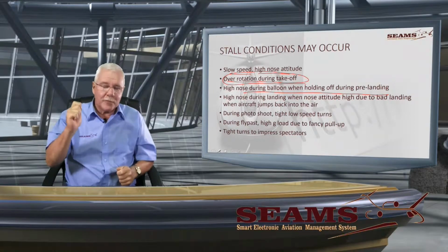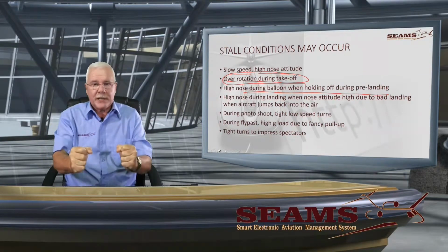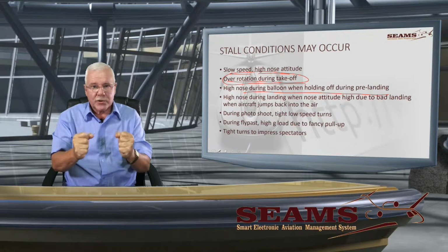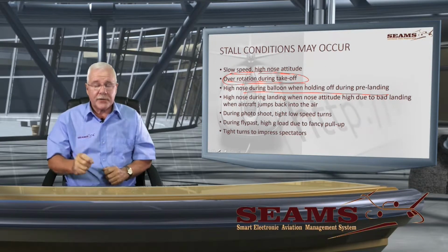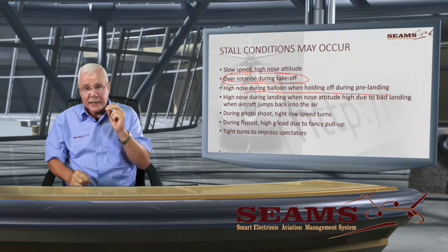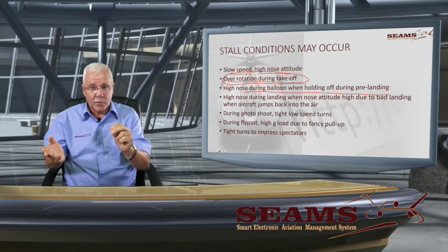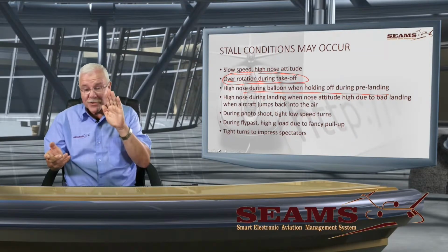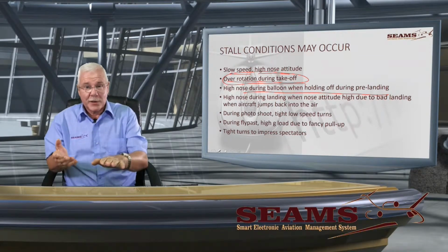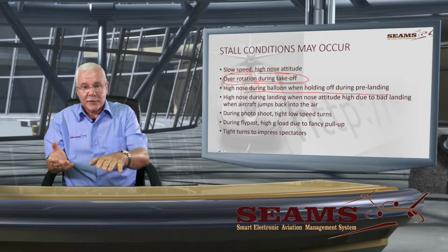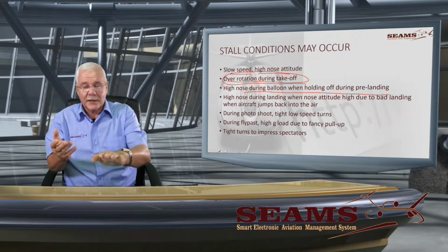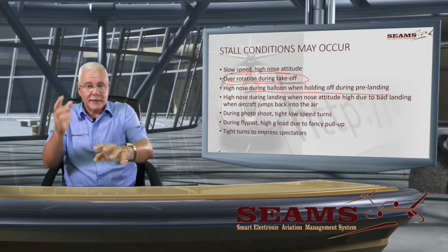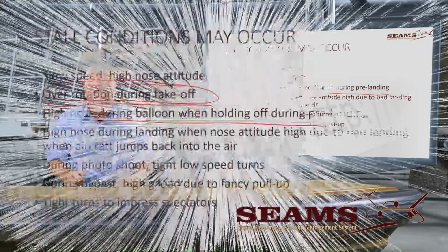It means to take full power, make sure that she does not over-rotate, make sure that you can control the pitch, retrim the aircraft, and let it accelerate. For every 5 knots, 1 flap up. This is now where it's important, okay? So we're taking off, we've got full flaps, accelerated 5 knots, 1 set. 5 knots, 1 set, 5 knots, 1 set. Finally, the flaps up. All right.